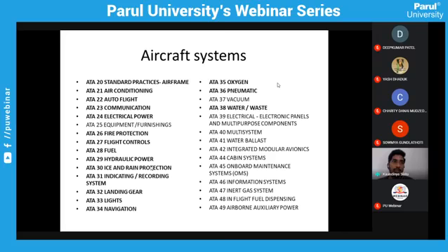Loops are nothing but a continuous detection sensor, depending on the material: chromium, nickel, and inconel tubes. Those types, and generally fire sensors, are mainly described as fire sensors, single point sensors, and the fire loop. So depending on where you have to use them, it will change. Again, it's a big topic.